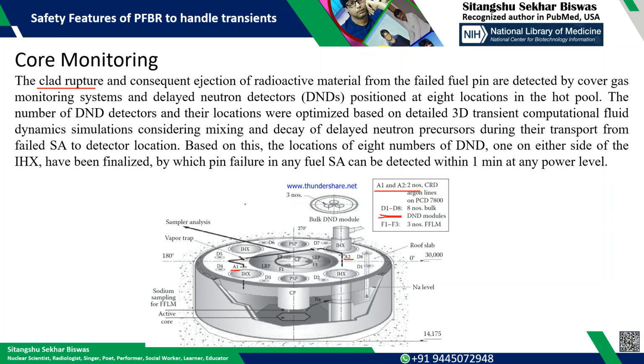If you take a 1 to 1 scale, then once it is meshed there will be a very huge degree of freedom, and your boundary conditions should be very favorable to converge the solution. Sometimes you have to do some approximation, and definitely that should be a fair approximation to converge the solution.